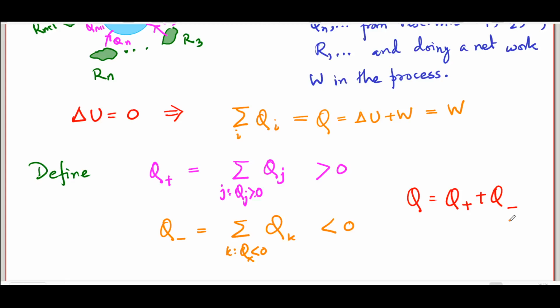Now, what we want to get out of a heat engine, of course, is the work. W is the output of the heat engine. Heat, of course, is what is the input. But here, note that the input really is not the entire heat Q, but the heat which is actually supplied to the system, Q plus. Only a part of that is actually converted into W, since Q is actually less than Q plus. The rest, Q minus, essentially is a waste, so to speak.